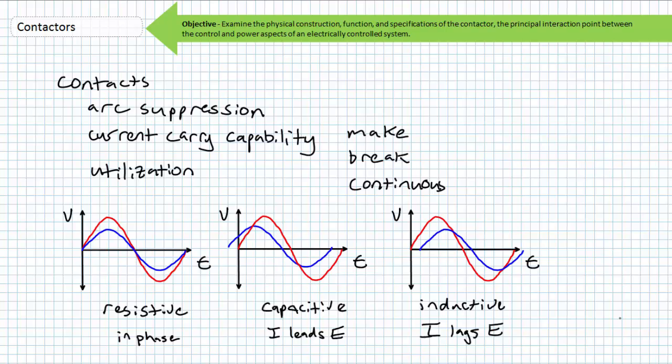Finally, the specific application of the contactor must be considered. Repeated opening and closure during locked rotor conditions will electrically wear the contacts. A locked rotor is a motor at rest. When first energized, a motor experiences an inrush current, often 6 times in excess of its regular full load current, for reasons I'll explain in other lectures. A motor that is being jogged or inched means the motor is only briefly energized and allowed to return to locked rotor or partially locked rotor conditions before being energized again.